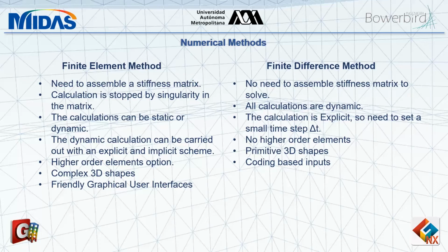That's a major contrast to FDM, where most of those software packages are code-based, so you have to know how to program. The shapes of the meshes have to be limited to a base of 3D primitive shapes, and they cannot use higher order elements. All their calculations are technically dynamic. They just use very short time steps to approximate what would essentially be a static case.